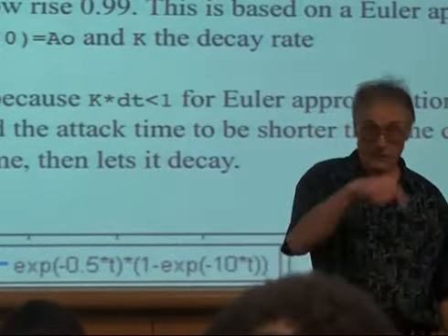So in the control thread, you could yield for 5 milliseconds before you go into the while measurement loop, and allow the first zero crossing to occur, the first blade crossing to occur, the first 2 blade crossings to occur, before you try and control this thing. So you turn on the motor to full speed or 3/4 speed. You wait for a couple of crossing times, then you start running the control algorithm.